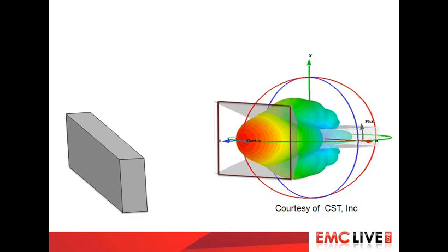The reflective power has now become a bit of a problem, because as you can see there, there's a good chance that if it's a large EUT with a beautifully screened front panel, as we would design into it, because we don't want impinging RF to get into our system, a lot of it could well be bound straight back into the aperture, and the amplifier will see it. Thank you, Mother Nature.